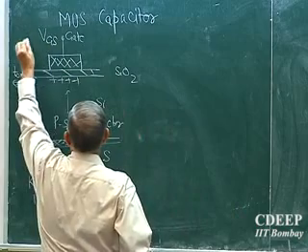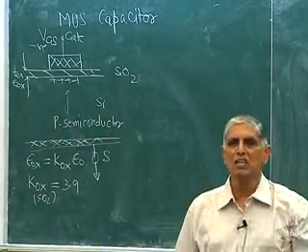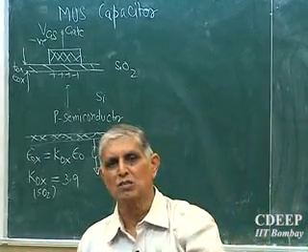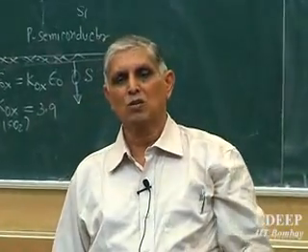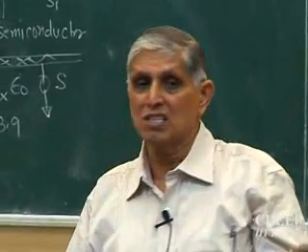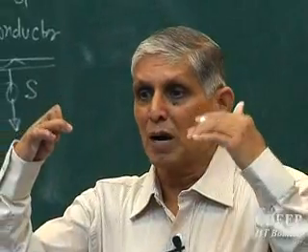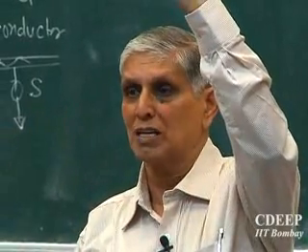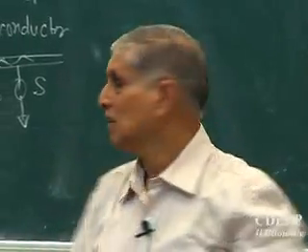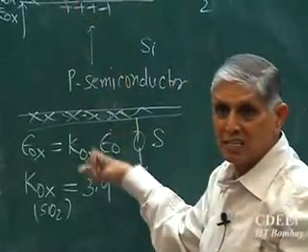Because the negative charge in the metal must be compensated, the induced charge must be exactly equal to the semiconductor charge, and all other semiconductor is charge neutral. Is that part clear? All other semiconductor part is charge neutral, but you have put extra metal charge, so at the surface there must appear a positive charge, which is due to holes, and these holes are coming from the battery. Is that correct?